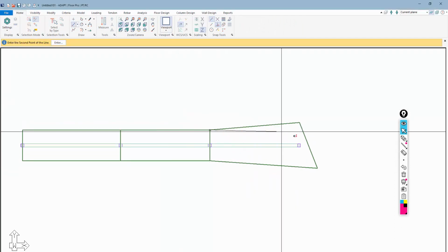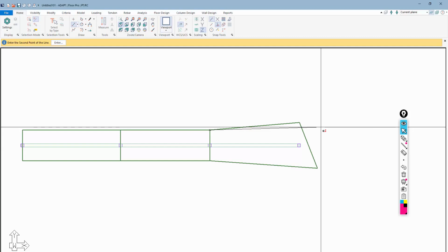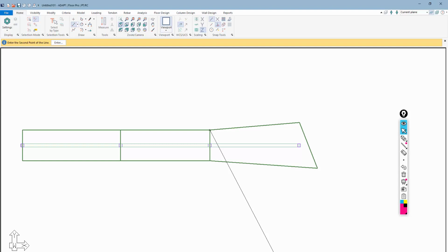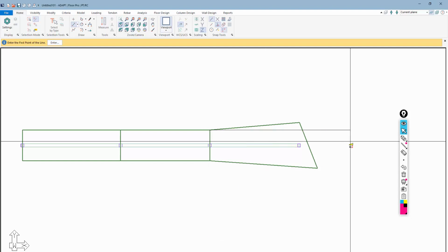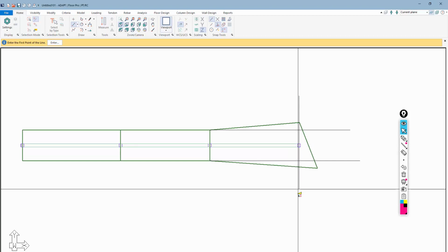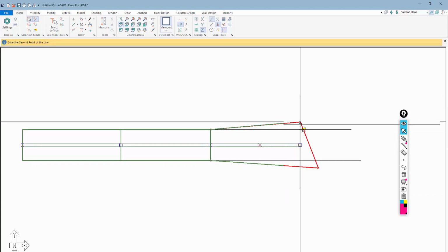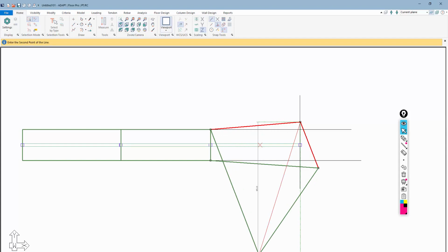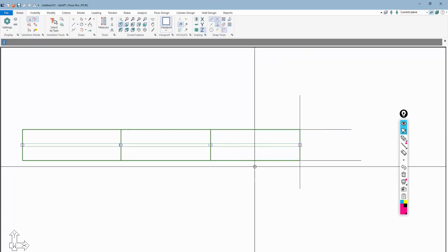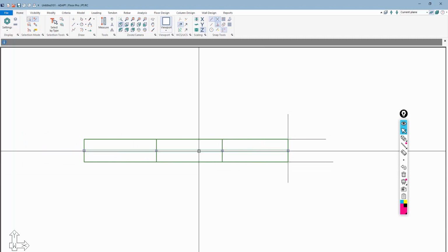Here I want to have this, in the orthogonal, let's say X direction, parallel with these beams. So I could turn on this option for snap orthogonal, and that allows me to align these construction lines orthogonally. And here I can just grab that and now just move it down. So there's different ways to kind of model the components natively and align things. This is just one particular way of doing that.